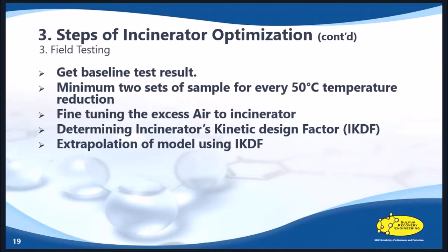One really interesting thing I'd like to mention is SRE's capability of processing samples in a very short time frame. SRE uses micro GC, which can process a sample in 5 minutes. Whatever samples we collect at the stack top degrade with time. With this capability, the degradation time is reduced and there is less chance of compromising those samples. SRE's in-house TRS modeling software will be used after all this testing is performed.